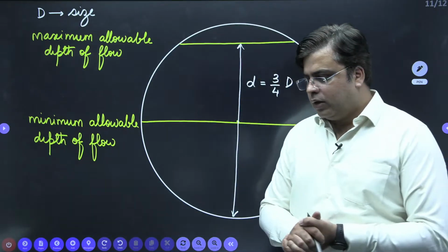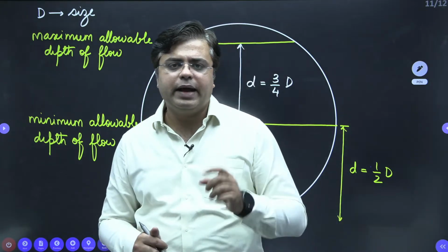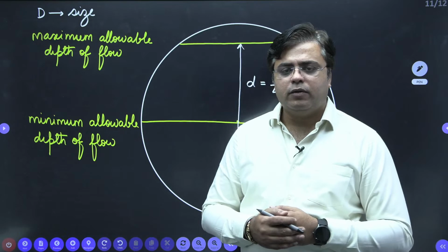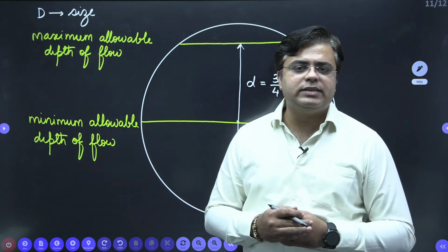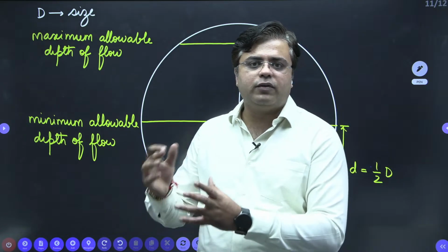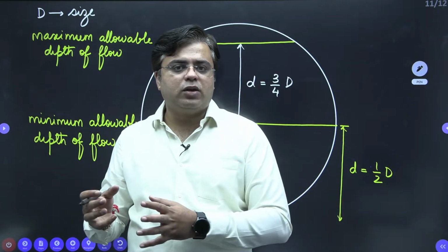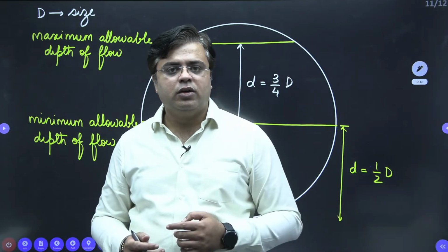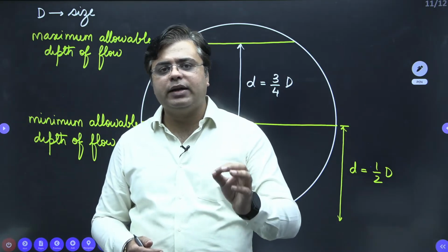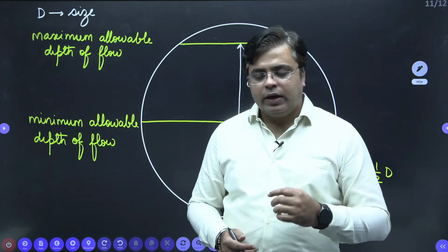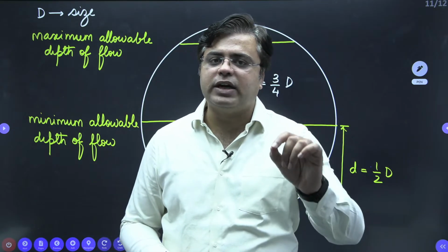Okay. Now this is something related to depth of flow. Moving ahead, I need to tell you one simple thing. Whenever you are seeing these sewers, the wastewater inside these sewers flow under the action of gravity, right? We are not using any pumps to suck or transport this wastewater. All the flow which is happening inside this sewer is happening under the action of gravity. If the flow happens under the action of gravity, it is termed as open channel flow.